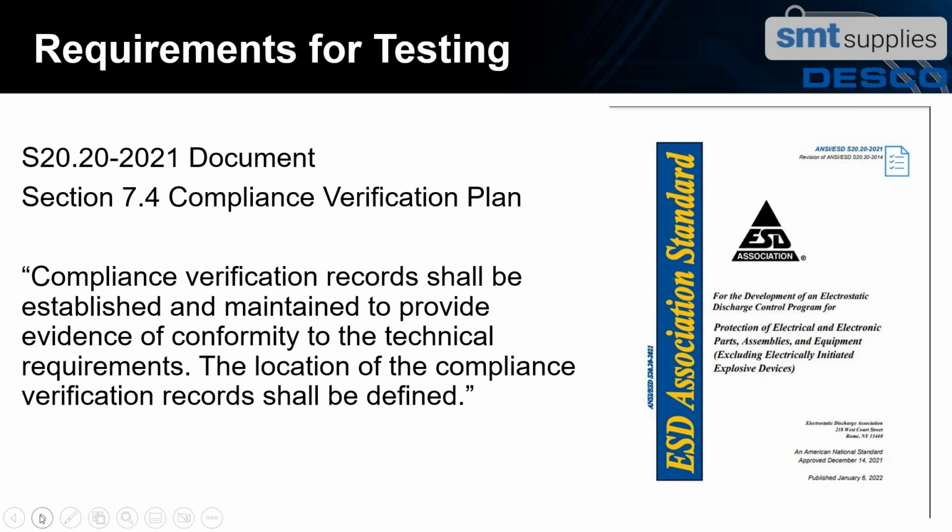That's available now too, but there needs to be some kind of record keeping when it comes to personal ground testing. And in the old days, it was all about, I'm going to talk about touch testing, keeping a written log in your EPA. And that written log also needs to be easily visible by the employee, and especially for you as ESD coordinators to review that test log from time to time.